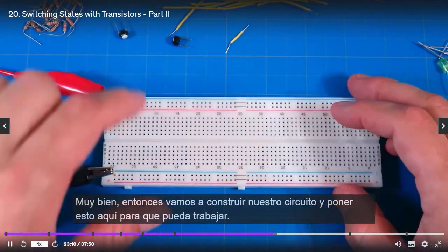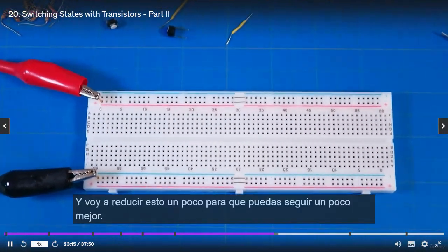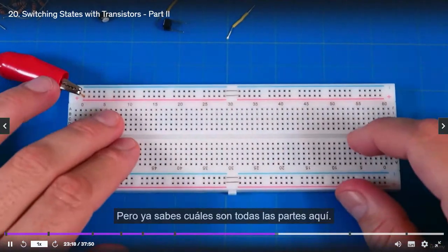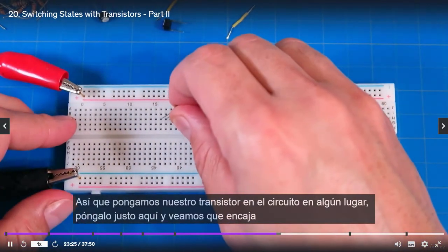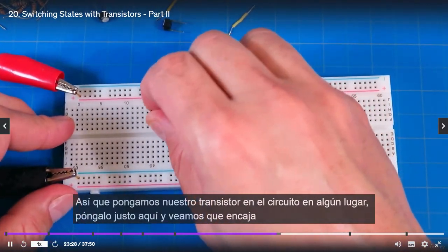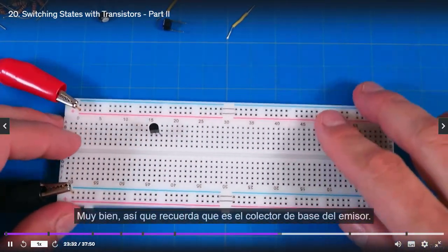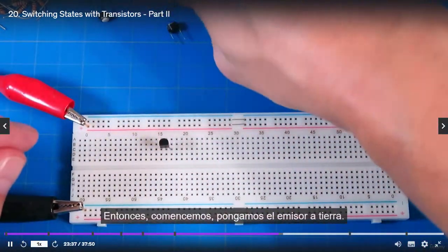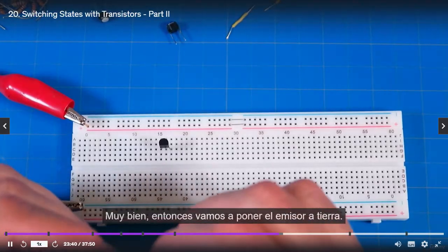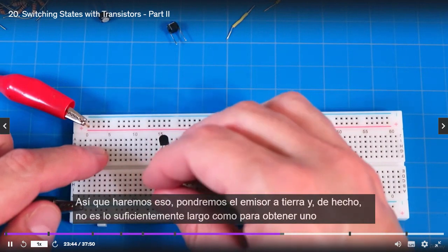Let me get this in here so I can work. Okay, and I'm going to bring this down just a little bit so you can follow along better, but you know what all the parts are here. Okay, so let's put our transistor in the circuit someplace. Put it right about here and see it fits in there nicely. All right, so remember, it's emitter, base, collector. Emitter, base, collector, right? All right, so let's start off and let's put the emitter to ground. So we'll do that.